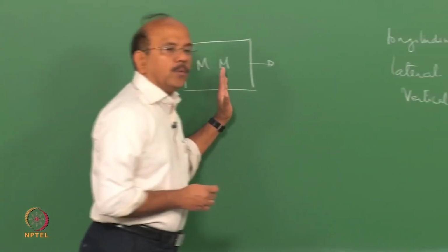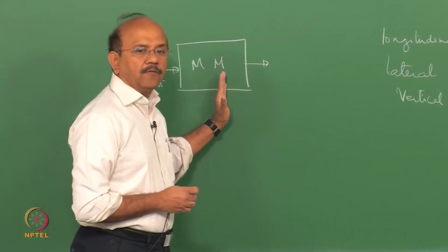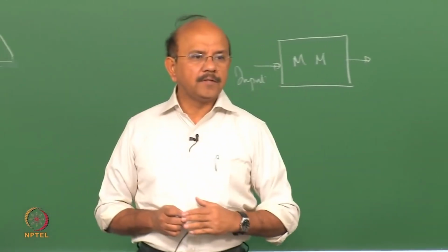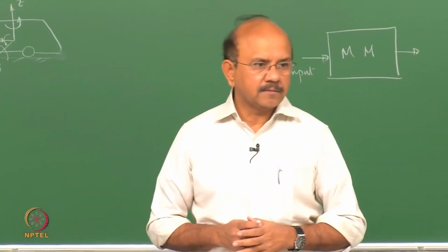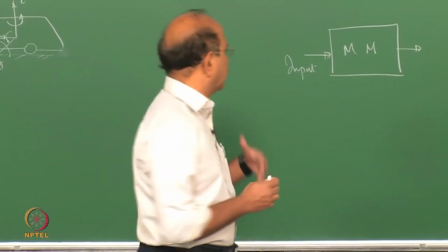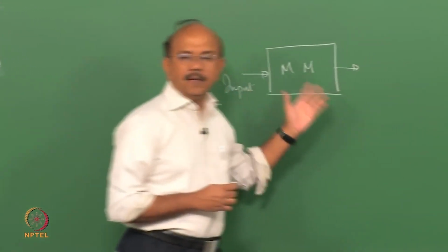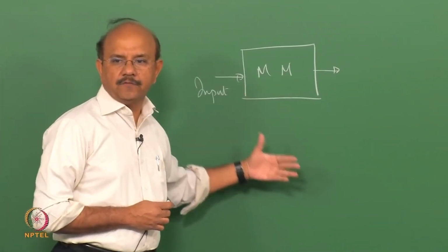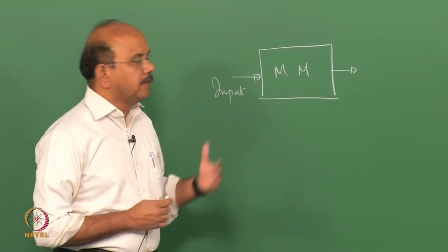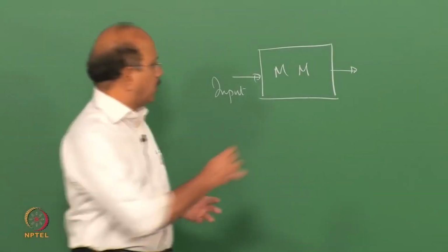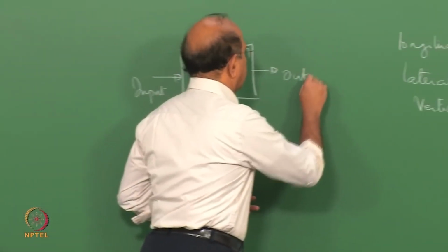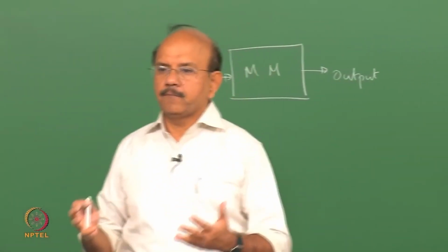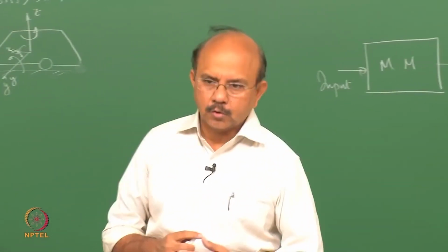Of course, we said that the vehicle itself, which goes into this mathematical model, will be defined by means of certain parameters, what we call kinematic and compliance parameters, mass, moment of inertias, compliances, stiffnesses and so on. The output from this model, as we said yesterday, are in terms of displacements, accelerations, velocities and so on.